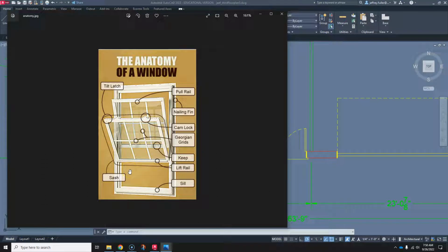Okay, now again, that 5.7 square feet is also a minimum. So don't get fooled by the minimums, because that's all they are. It's a minimum. If you want to have a larger window, by all means, go ahead and have one. But don't have anything smaller than that. 5.7 square feet of open space, no less than 20 inches wide, no less than 24 inches tall for the opening space.